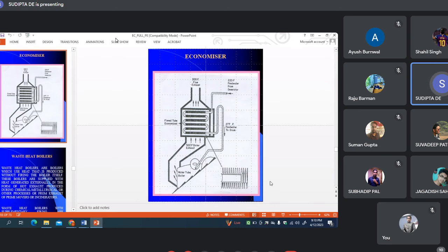Now, steel tubes must come with fins, otherwise I cannot improve the heat transfer. There is also an extra small but very important issue: the fin structure has been shown here in an extended view, so the outsides must always be finned. Now the important issue is the flue gas passing through, shown here as 500 Fahrenheit to 300 Fahrenheit; you can convert it into corresponding temperatures.